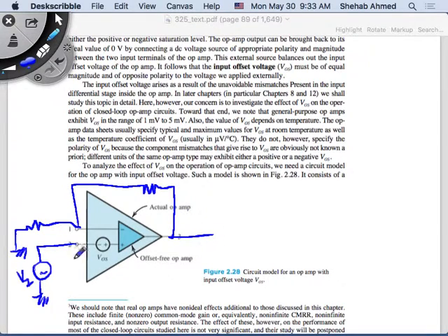Right? If your signal is 0, so I'm bypassing this, I have feedback, which means that the difference between these two is 0, which means that the voltage here is 0, so there's no current going to flow here. So I have 0 at the input of the amplifier, theoretically speaking. If you do that, what do you expect at the output? Theoretically 0. But you're not.